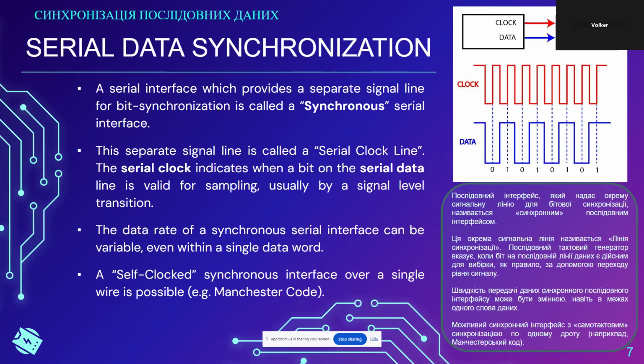And if the serial data communication is interrupted for a short period because something with higher priority is happening, it does not matter to the receiving device. So even in the middle of a data word, it is possible for an interruption to happen. And the receiving device will just patiently wait for the next rising edge to take over, to accept the next bit.